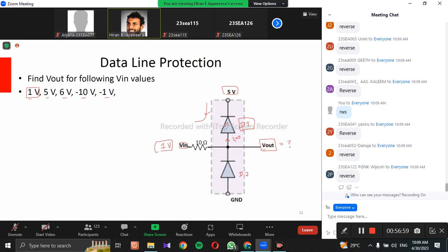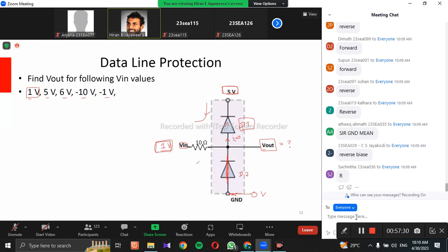Right. Most of you say it's reverse bias, but very few say it's forward bias. Now let's take a look at this carefully. This is connected to the ground, right? So what's the potential here? It is 0 volts. Everywhere else you have a power supply: here 1 volt, here 5 volts. If you didn't have a diode and just connected this with a conductor, would the current flow towards A or B?